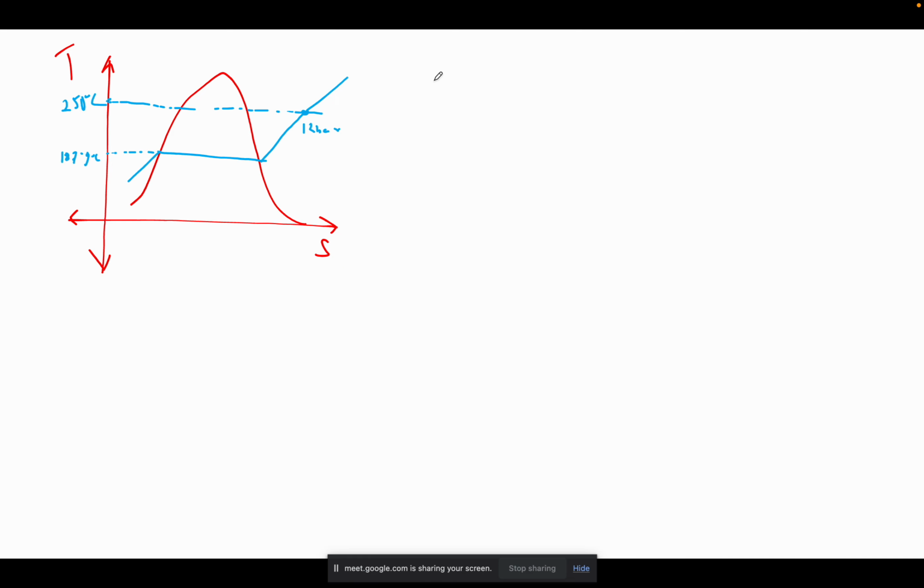So that means if my T value is greater than T saturation at a given pressure, then my steam is superheated. Now this is already told to us, but I'm just giving you a brief idea how to check if this had not been told to us. So this is in the superheated state.